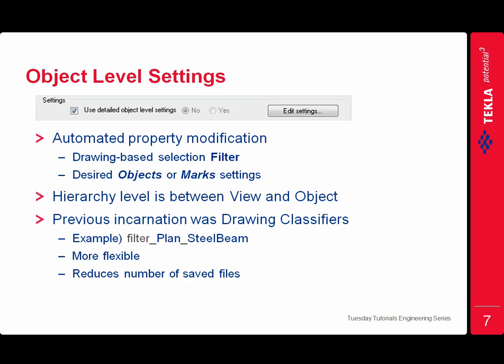And with the view level, you can go through and you can change the view level settings that apply toward the objects, and if you've changed it at the manual level, then the object settings will stay. However, if you use this object level settings, once you switch the views, the objects will change according to the settings associated with that view setting.